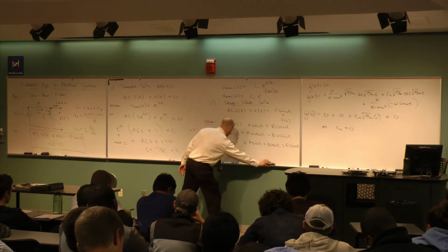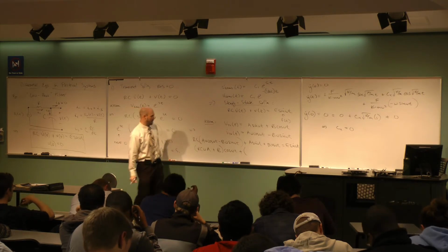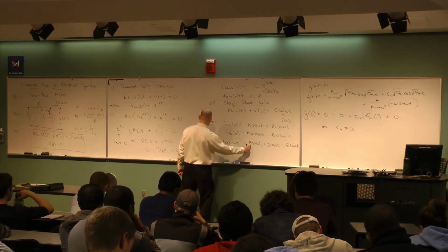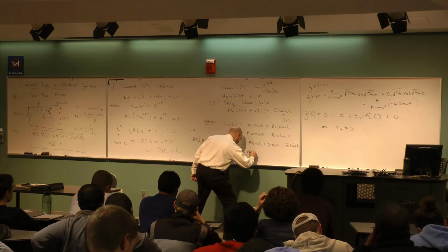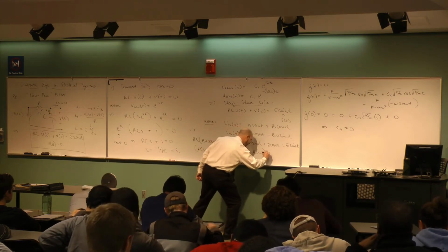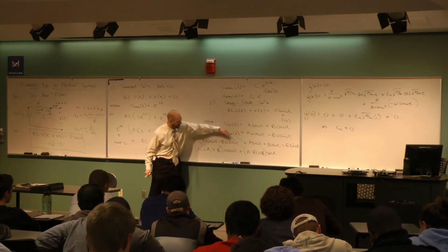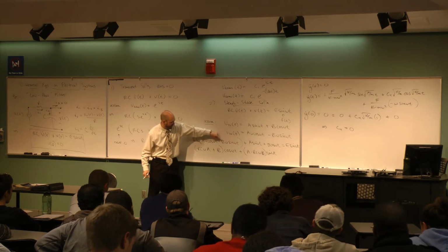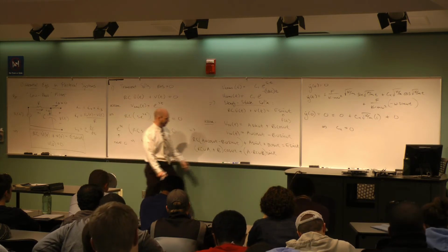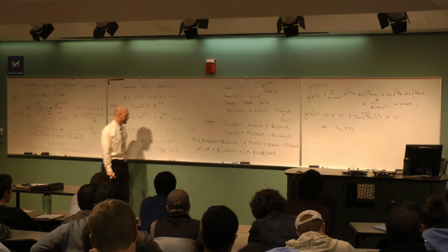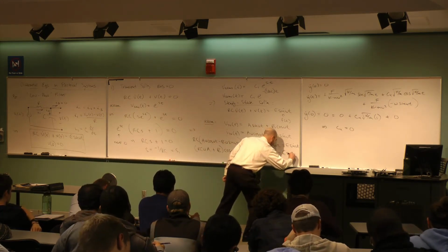What would multiply by the sine omega t on the left side of the equation? Yeah, I've got an A right here. I got RC omega B, which is negative. So I might want to write this as A minus RC omega B times the sine omega t. So again, check the terms. Here's the sine omega t, RC omega B negative. And then here's the A sine omega t. I got that one there. And then finally, on the right-hand side, I've got E times the sine omega t.